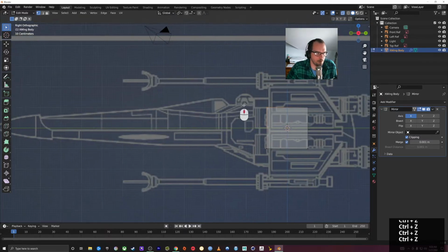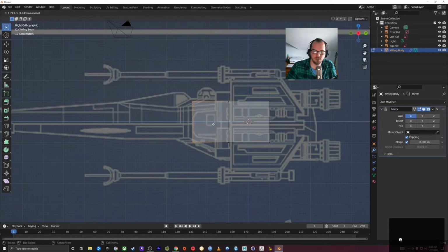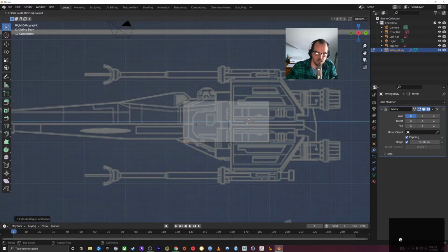All right, so we're back at a square. What I'm going to do is grab all of this front face here, and just kind of extrude different parts out where the shape of it changes. So with all of these front vertexes selected, I'm going to hit the E key and just kind of extrude out to here, like that. Because now it seems like there's a little bit of a change in the shape, so I'm going to E again, and maybe S, kind of scale this up, maybe G.